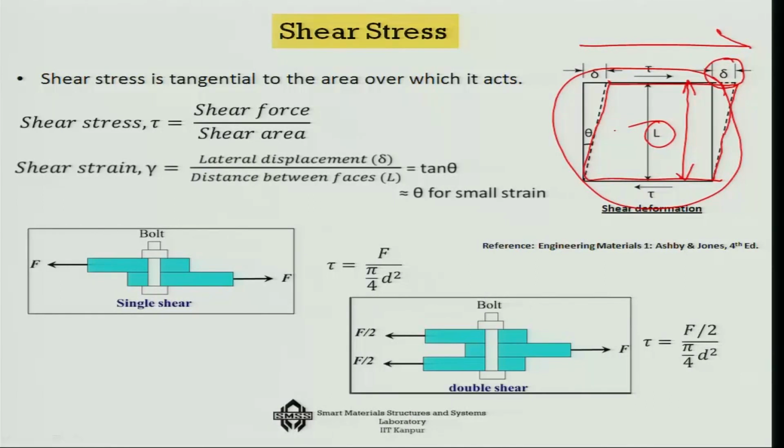So, you may also express it as tan theta. Now, whenever this is very, very small, then you know that tan theta becomes almost equal to theta, and hence for small strain condition, shear is often expressed in terms of the angle theta. Okay. Now, there are many day-to-day examples.